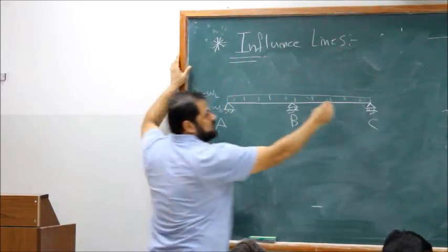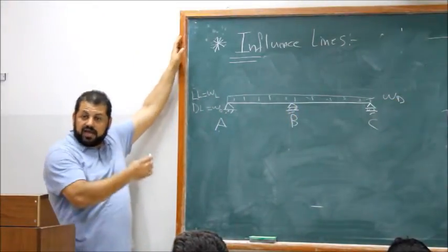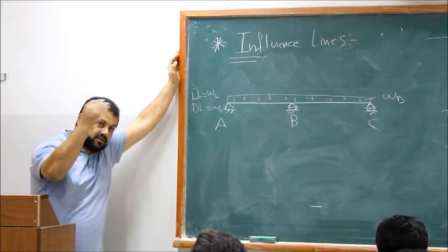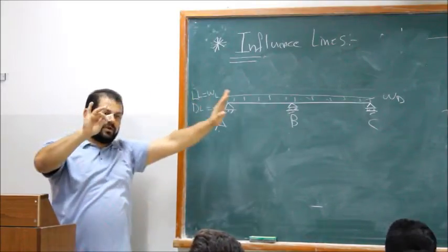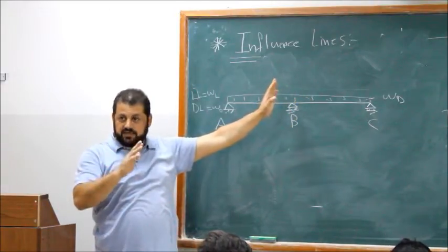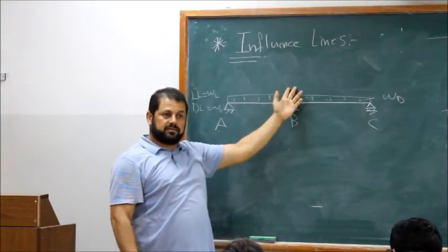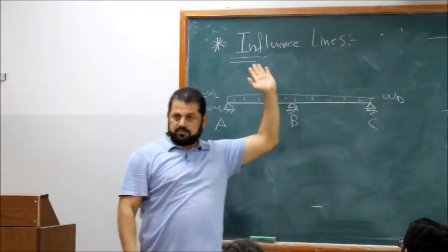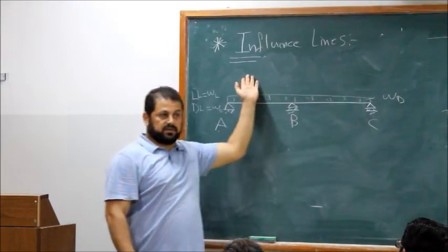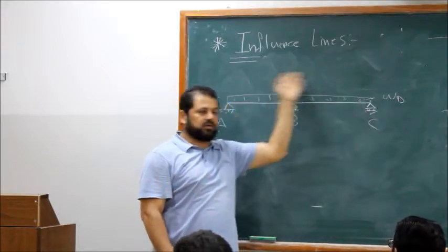On both spans. This is W dead, right? And the live load changes. The maximum shear on the moment is from the distributed live load, depending on whether it's positive or negative, meaning on both sides. Good. He says it can be all the way, it can be on one span, it can be on the other span. It could be here alone, here alone, or on the side. Either one span or the second span, the first or second or both of them.